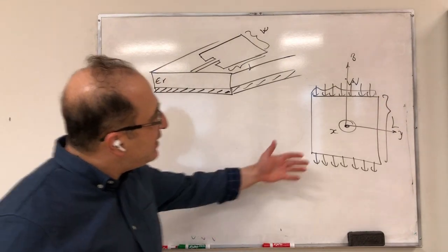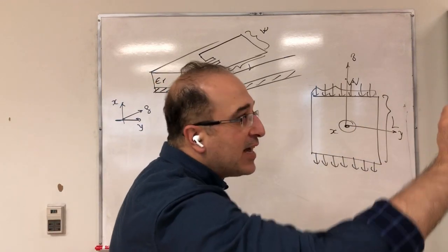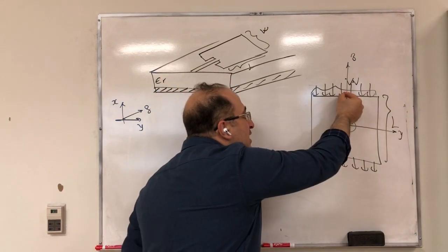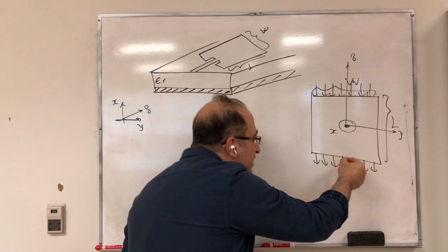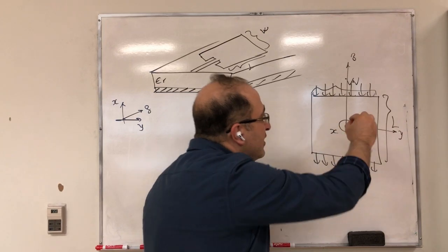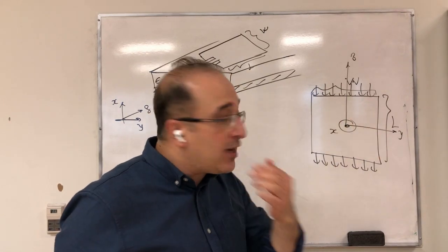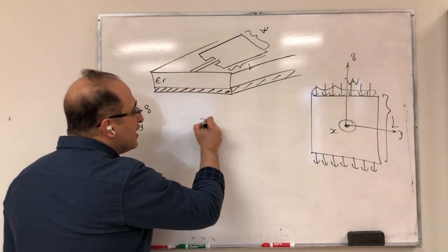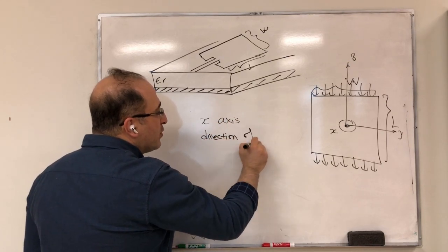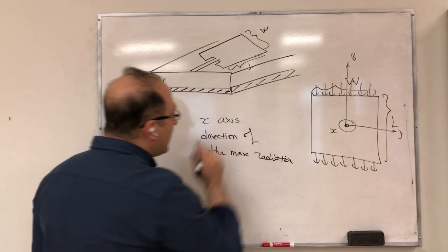Now, if you look at the way that they radiate, first of all, you notice that these are in phase. If I'm on the x-axis right here, the distance from the observation point to this radiating slot or this radiating slot is the same, and they also have the same phase. So they add constructively over the x-axis. Everything would be in phase on the x-axis, so the x-axis is going to be the direction of maximum radiation.